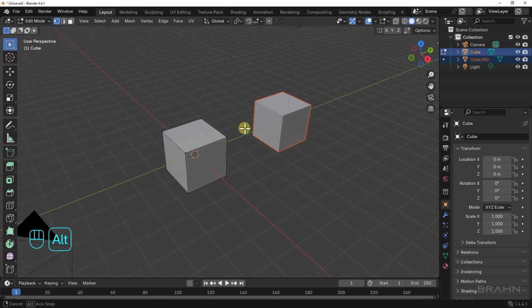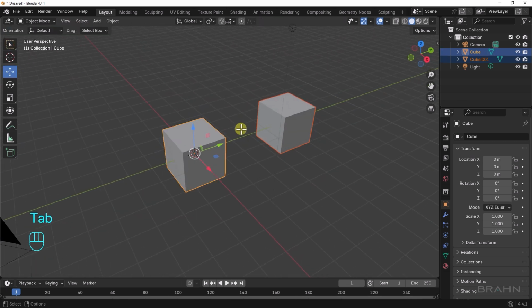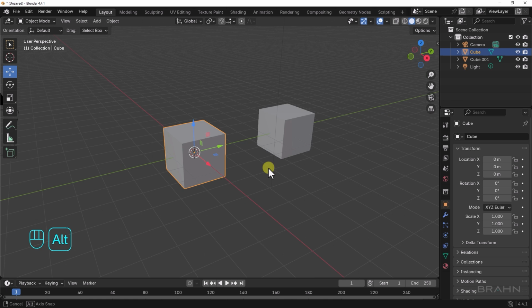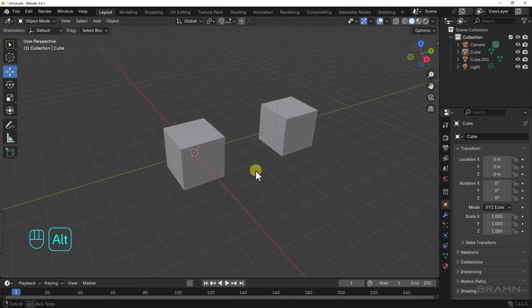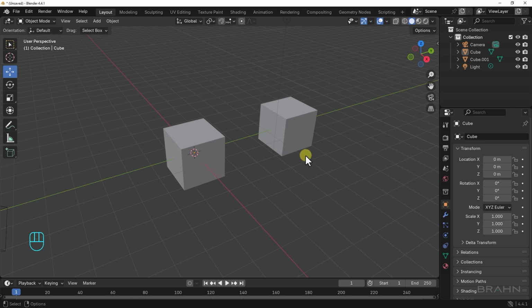Toggle back into Object mode with the Tab key. You see once again, they are separate meshes in the viewport, and in the outliner as well. Because this is just an introduction to modeling video, I won't go over the literally hundreds of hours that you can spend modeling some very complex creations. The last tool, which is really a modifier before we go, is the Boolean modifier.